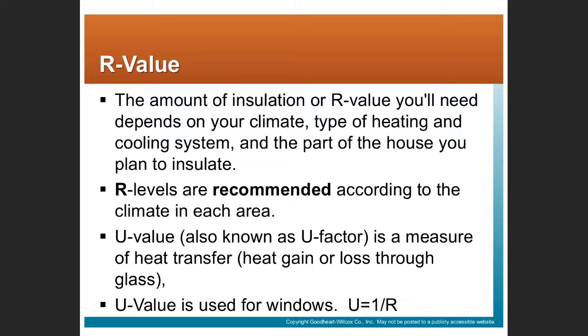So the building code, either the IRC, the International Residential Code, or maybe the IECC, International Energy Conservation Code. Remember those I codes from a couple weeks ago, those model codes. Those will stipulate the amount of insulation or the R value of the insulation that you need in the walls or roof.